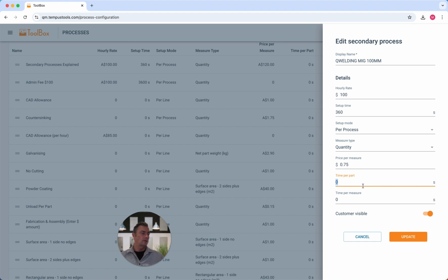That's used for loading and unloading. So imagine you've got a pallet with the part on the pallet. You're grabbing the pallet, putting it on the bench, clamping it, and then a repositional time. All of that takes 15 seconds. Then this time here, the very last one, becomes the time to weld 100 mil of MIG. So let's say that's 30 seconds.